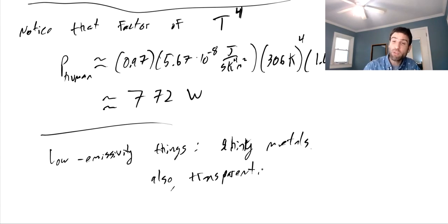A shiny material doesn't absorb electromagnetic rays because it reflects them. So there's shiny aluminum foil, there's an incoming bit of thermal radiation, and it just bounces off. In contrast, transparent materials don't absorb that radiation, but it just lets it right through, right? And you've probably noticed that when sunlight is streaming through a window onto a patch of floor, you have a warm spot on your floor, because the window hasn't absorbed very much of the thermal radiation. You get a warm floor even when the window itself is staying cool.